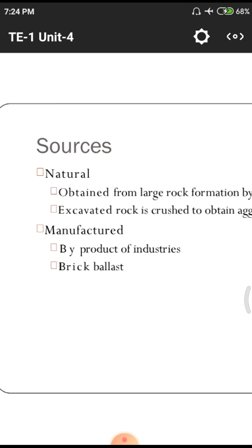Likewise, we are using different things like coarse aggregates and fine aggregates. Normally those are all naturally occurring. By using them year by year, all those natural things will disappear after a few years, like 50 or 60 years. There may be no hills or other natural resources for our construction purpose, so we need to reduce the consumption of natural resources. We have to use industrial wastes in our construction purpose, replacing 30 to 50% or sometimes 60%.